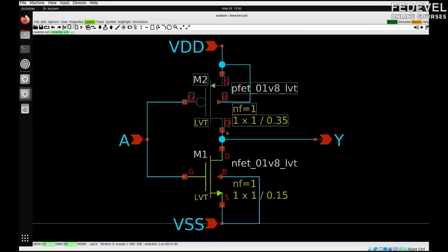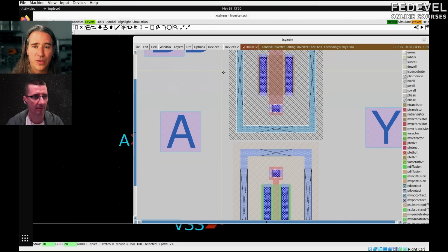Where they're touching is going to be on the right, and the two gates here. One of the sides goes to VSS. So this is a very simple circuit too. We're just going to bring this one up, bring that one down, have the gates come in from A, and have the two ends here connect to Y. Okay. So all we have to do is...